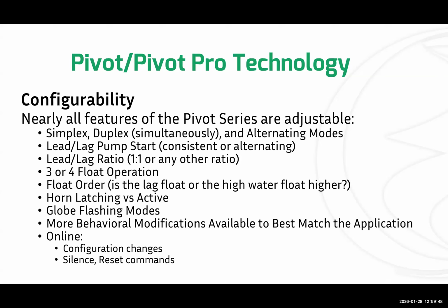All right, but that's customizable in there too. The order of the floats, whether lag is actually on top or high water is on top, is something you can adjust. Whether the horn stops screaming when the alarm goes away or whether it continues to scream. So let's say you have, I'm trying to think of a good example of this.